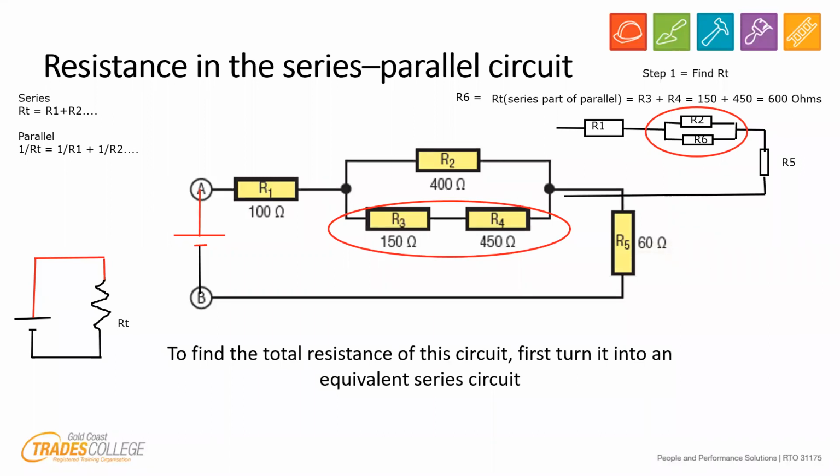Okay, so if I come underneath, now I'm doing what's in the second circle. All right, so my resistance total of the parallel is going to be 1 divided by RT equals 1 divided by, now it's not R1, not R2, like our formula usually is, because we're not using R1, we're using R2 and R6. So just be careful with that, all right? That's an easy way of making a silly mistake and using the wrong numbers. All right, 1 divided by R6.